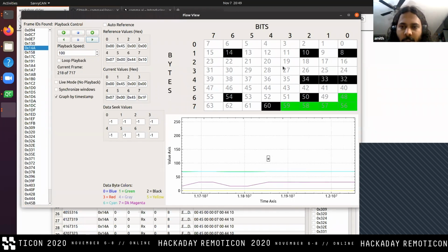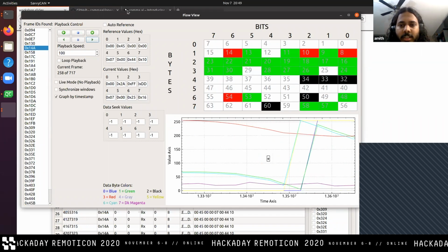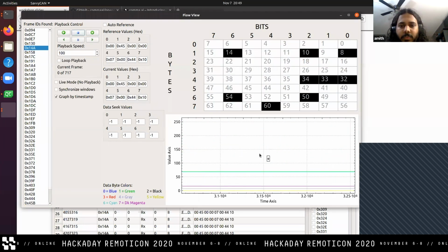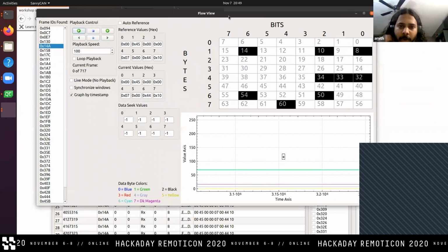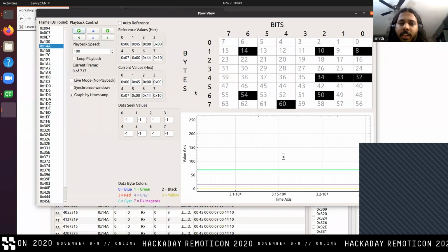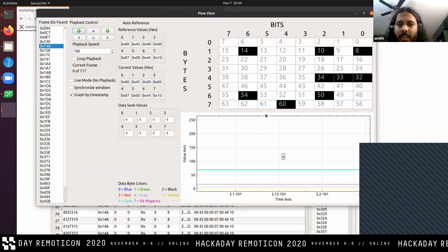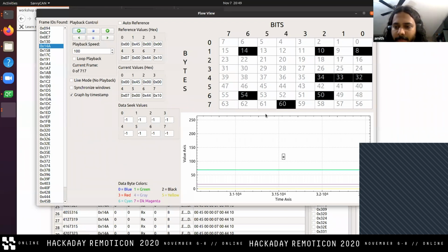Let's see. Okay, there. Right here, I think it'll just jump up here. I'm just going to stop it. So before, from previous knowledge, when we looked at our DBC file, we knew that 5 and 6 were our key bytes that our steering wheel sensor is stored into.